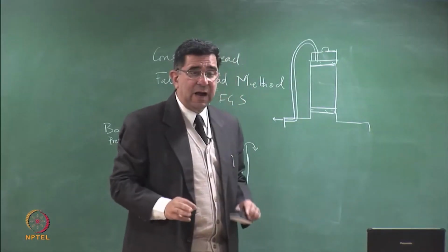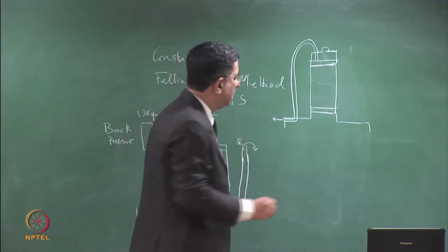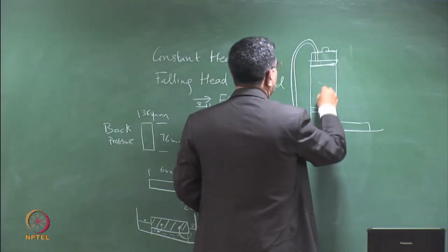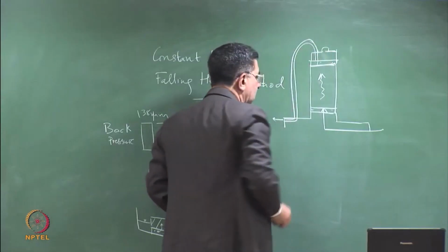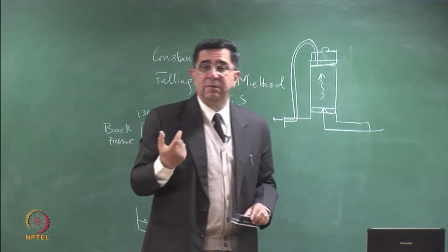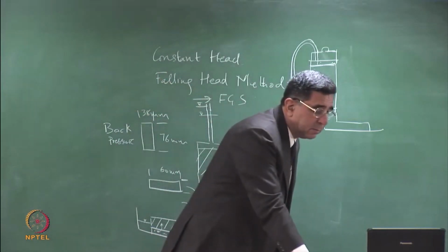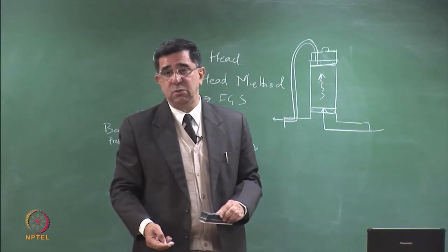So I do everything identical to the triaxial test except that I cause a head difference and I make water to flow through a sample with B factor equal to 1 and measure the volume change with time.